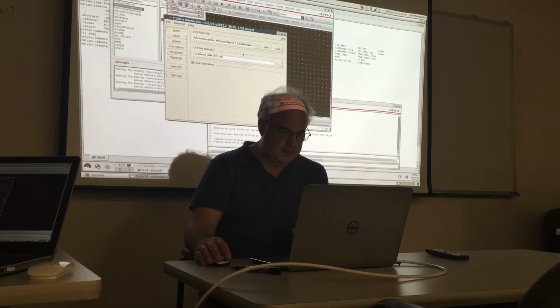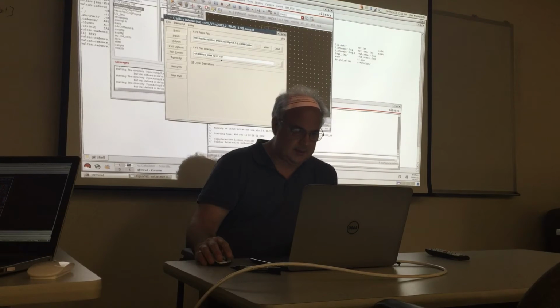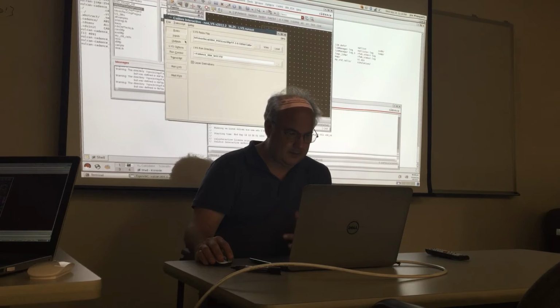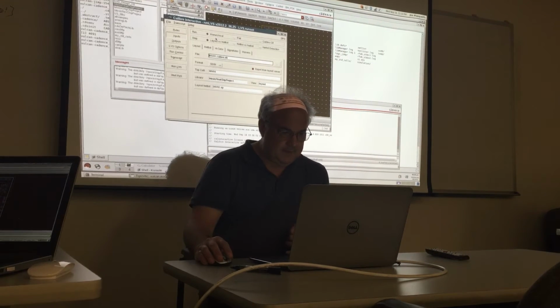When you get to PEX, there are some options that we have to talk about, but we're not going to do simulation yet. And then here, you just want to export from schematic, right? Make sure that that's set.